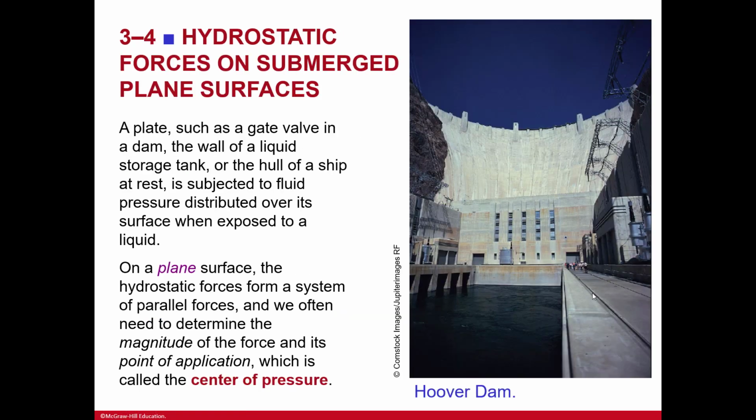So here are hydrostatic forces on a submerged plane surface. I'm not going to go into too much, but we will define what a plane is. On a plane surface, the hydrostatic forces form a system of parallel forces, and we often need to determine the magnitude of the force and its point of application, which is called the center of pressure. And that's Hoover Dam. It's amazing.